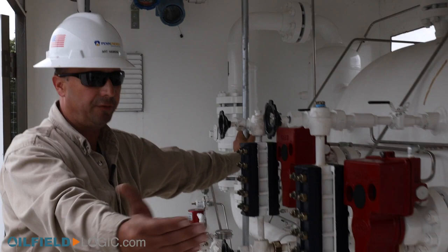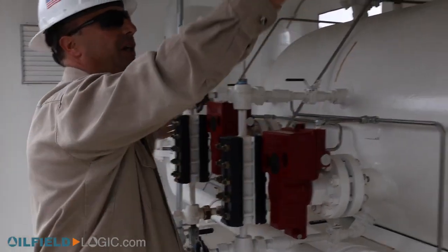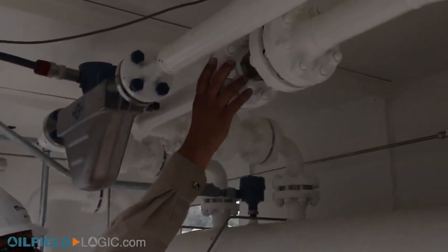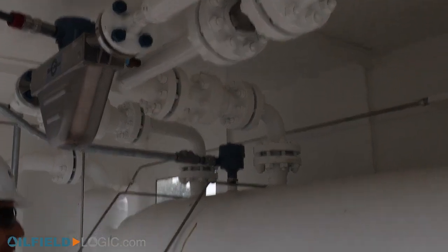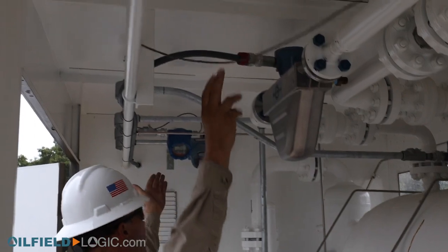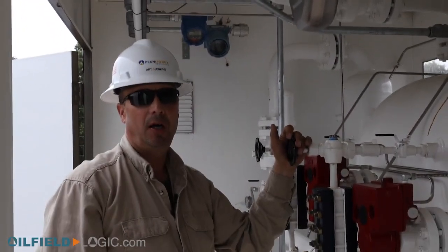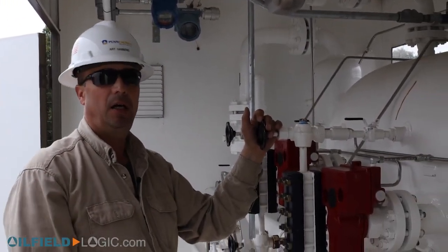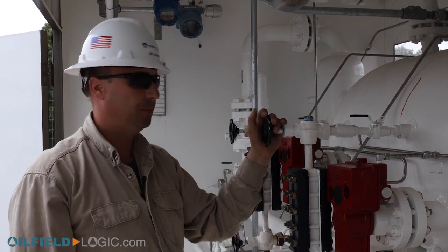We do measure the amount of fluids coming from the unit. We have the orifice meter for our gas stream. We have what we call a turbine meter or spin meter for our water side. This is when we open up, it's going to spin an impeller, send a pulse signal to a water meter and track that through our PLC to SCADA and to the operators and myself and supervisors.